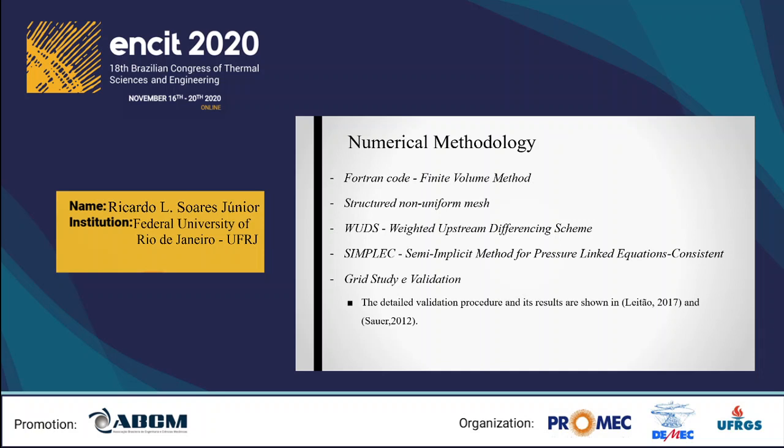Initially, a grid convergence study was conducted considering the limit case without irregularity. The streamline and temperature profiles obtained for three meshes were compared, and according to the gains in the result in relation to the simulation computational time, an intermediate size grid was selected for the present study. Besides the grid convergence study, code validation using numerical and experimental literature data was also performed.